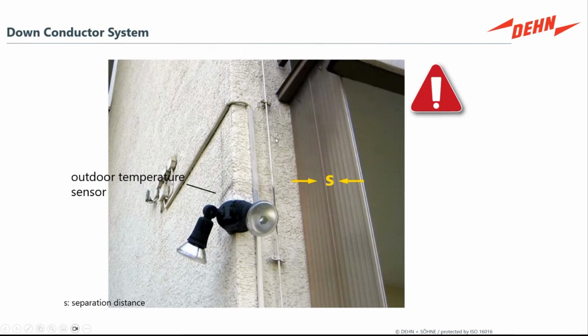There's your lightning protection system trying to do its job, but it's so close to some of this electrical apparatus that it flashes in. That will cause excessive damage on the inside of the facility that you may not otherwise have suffered.